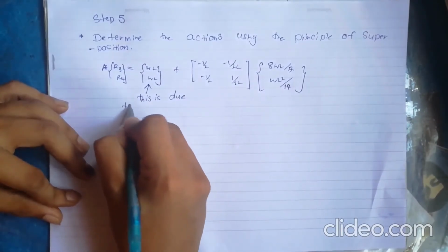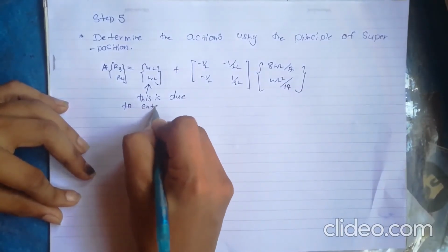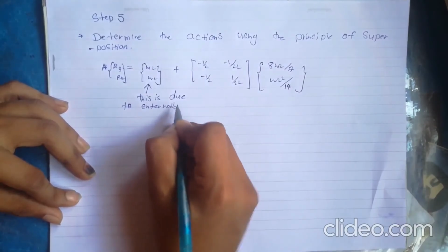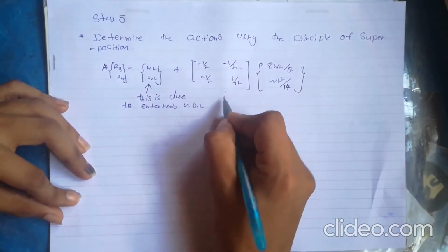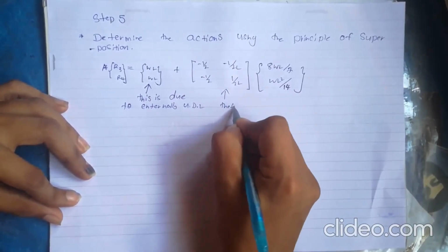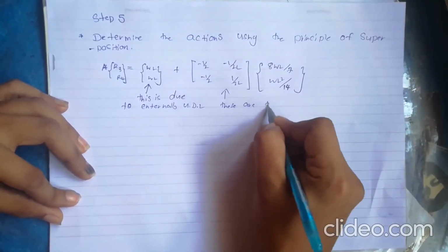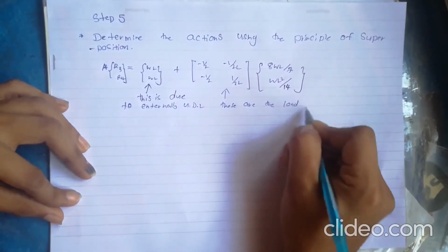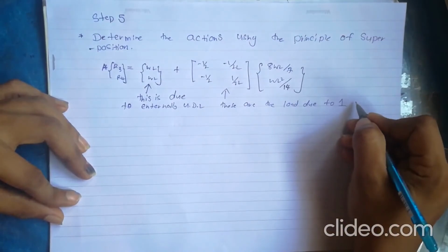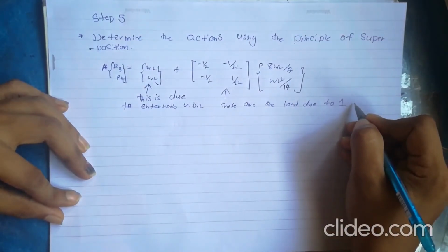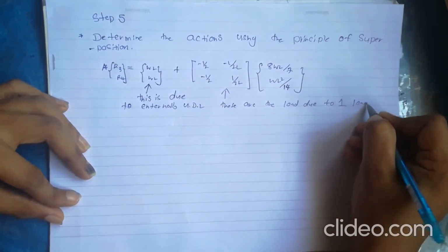These WL loads are the R3 and R4 values if we consider only the UDL, and these are the answers for R3 and R4 if we only consider the unit 1 reactions for R1 and R2. We need the real values of R3 and R4, so we use superposition.